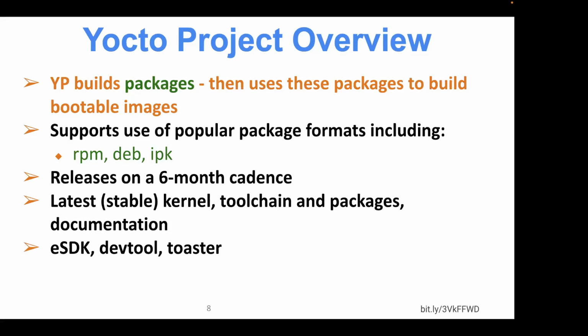In Yocto Project, we have an extra step, and we go through a build, install, package step, and then from the package step, images are then built. Now, this sounds like an extra step that isn't strictly necessary, and one could argue that it isn't. But the reason why this is really important is because by packaging things, the authors of the recipes that make up each one of the packages are deciding the classification of the different files that go into the different packages. What that means is that we can distinguish between what makes the binary, what makes the development files, the man pages, and so on.